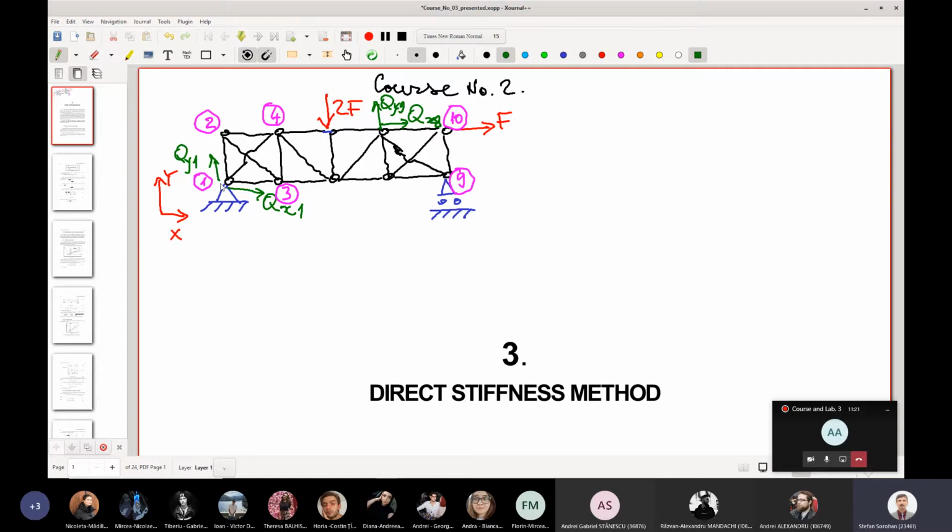joint here, in every node, as you will see later, we can have some forces. And for the forces, let's use another color here. It is possible to have a force here, which will be the reaction at this point. And here the forces will be the external applied loads. As you can see here, we do not have a load there, but here we have one. And this one is negative because, as you can observe, all the displacements and all the forces are positive if they coincide with the x and y axes. So here I can generally have a force Fx for node 1. Here I have a force Fy for node 1. Here I will have Fx for, oh, this is not 9, this is 8 here.